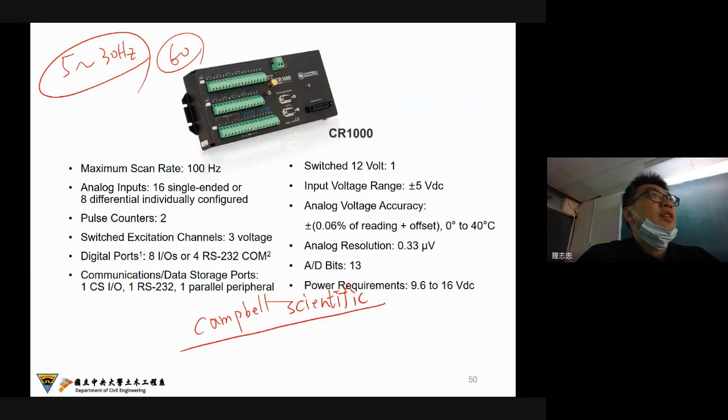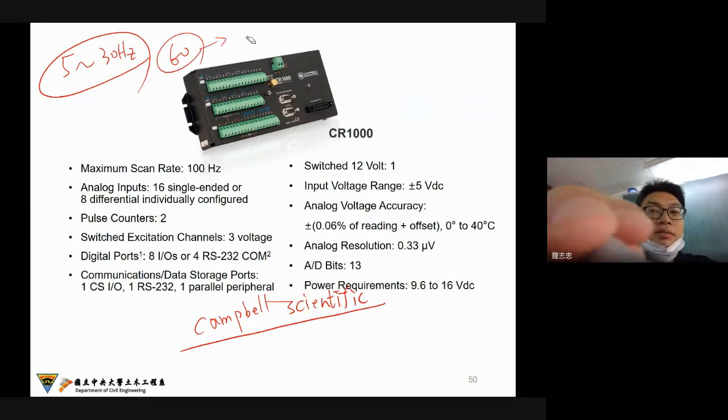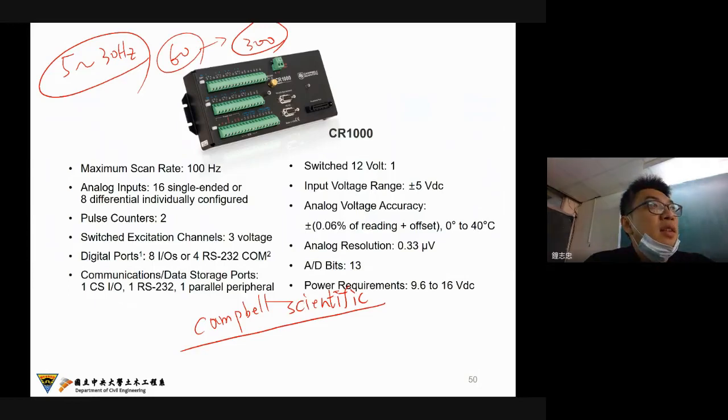But I would like to say in practice, maybe 10 times the frequency, the sampling frequency, we should use. So maybe we need to use at least 300.